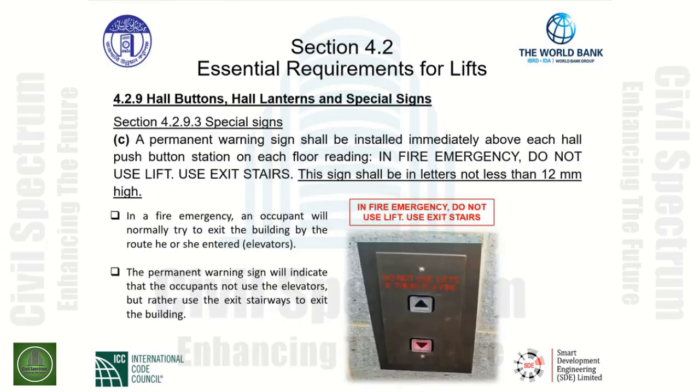Special signage in section 4.2.9.3, item C. A permanent warning sign shall be installed immediately above each hall push-button station on each floor, reading, "In fire emergency, do not use lift. Use exit stairs." This sign shall be in letters not less than 12 millimeters in height.